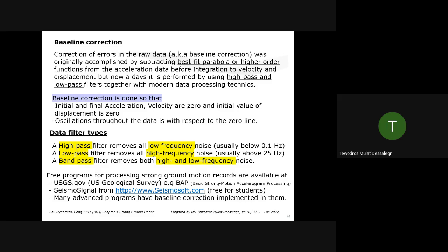That fine mesh requirement makes the model really large for the solution, and it may take lots of time. So the smaller the frequency, the faster the solution. We'll see that in detail when we go to the applications. If you are trying to capture higher frequencies, the meshing requirement is very high.